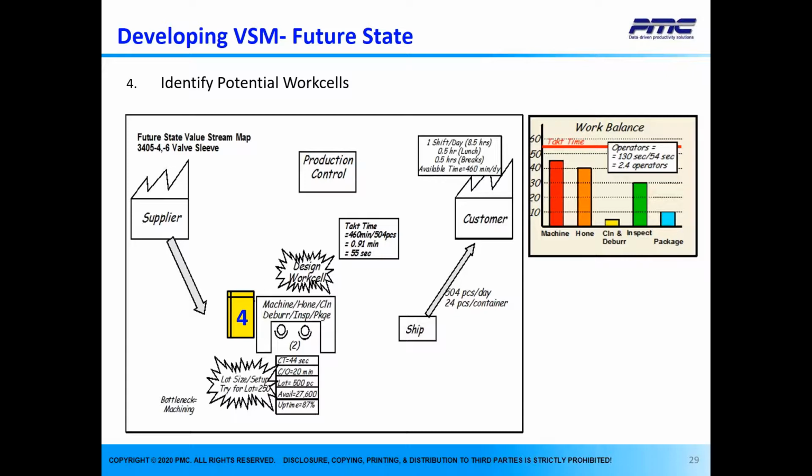High equipment utilization is not critical. The clean deburr process is run on specialized equipment in a central area. If clean deburr can be scaled down as a manual or semi-manual operation, it can go in the cell. This seems feasible and the team accepts that. So it will be done.